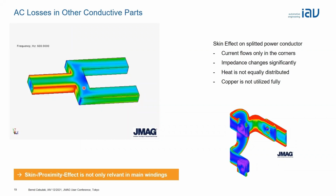The current stress on those bars can be very high. And if you are thinking about simulating the heating of those bars, you have to look at AC losses or current distribution regarding high frequency as well. That's the same also for conductive housings that are around magnetic fields. For instance, in DC-DC converters, if you are producing some reactor coils and you have stray fields where there are some conductive aluminum parts, you also have to look at the stray field. All this is possible in 3D with JMAG now.